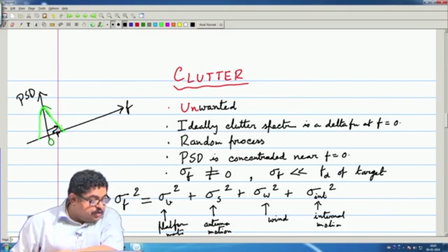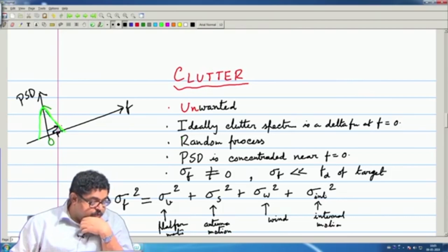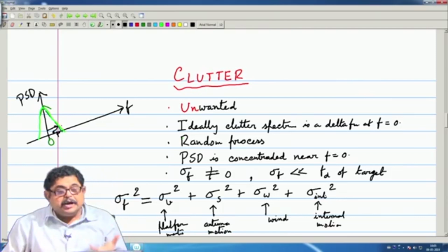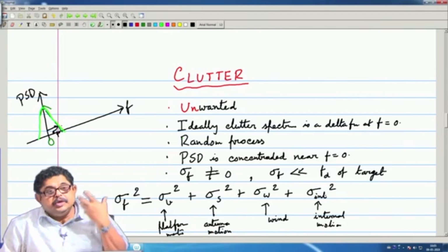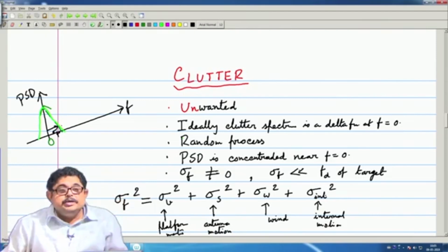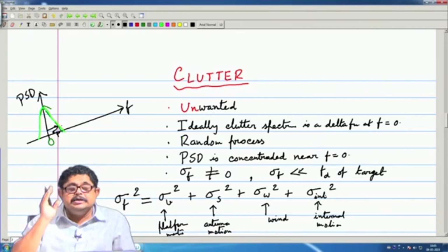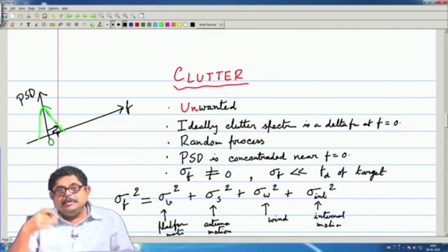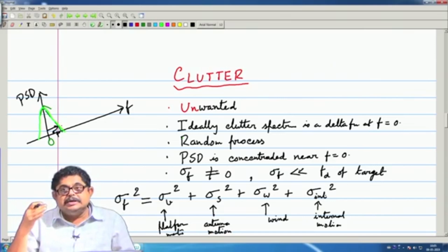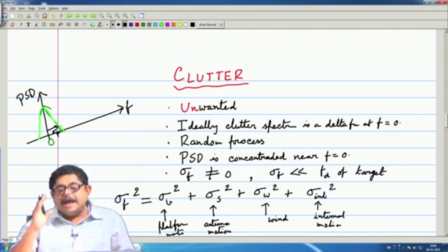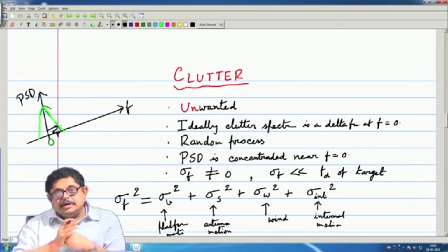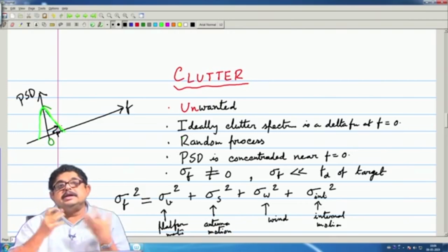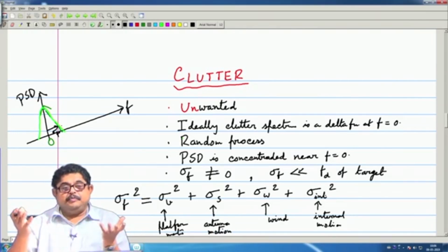Okay. Now, what happens if pulse radar, you can consider that a pulse radar is sampling the echo whatever it is getting. Since it is sending repetitive pulses, we can say that it is sensing or sampling the returned signal at a frequency FR.